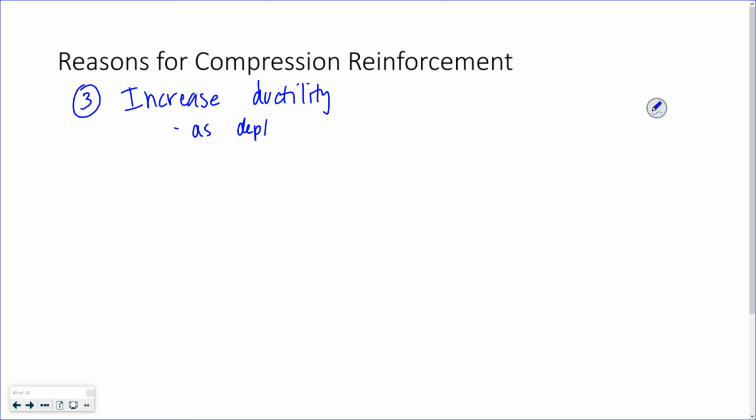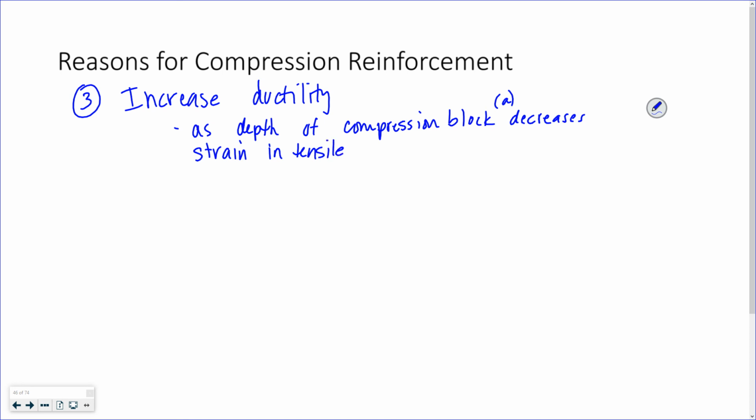As depth of compression block decreases, that's your A. As your A decreases, strain in tensile reinforcement increases.